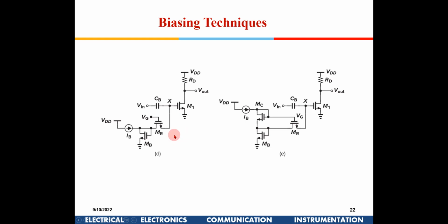So these are some of the variations. That RB resistance can be implemented by an NMOS transistor only. RB is nothing but, if you see here, the gate voltage is fixed here. This is the channel resistance, which could be in saturation region, it could be R0, a very high value. Because this is a fixed voltage out here, that fixed voltage again can be generated like this.